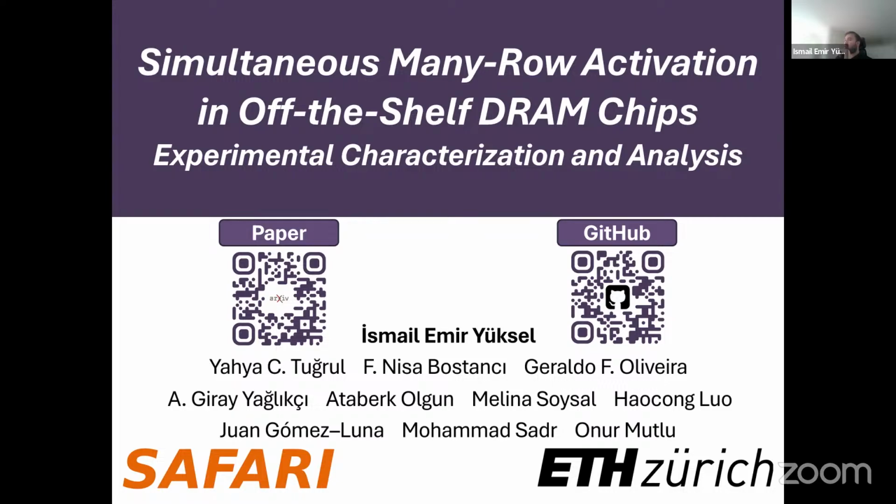No, right now, no. I think if you want to really enable processing using DRAM, we need some modifications. As you can see, it's a very hacky way of what I'm doing. There should be some official support. It should start from the row decoder circuitry, even the interface also, but inside the DRAM it should start from row decoder circuitry, and the cells should also